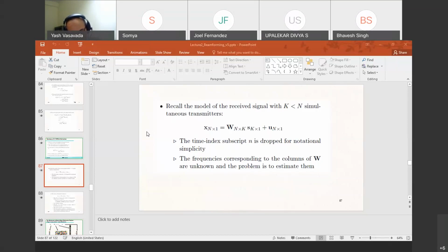In that context, we looked at several other windows, Hamming window, Hann window, the Kaiser window, etc., which suppress the side lobes. But it's sort of like Heisenberg's uncertainty principle, that there is a certain limitation in what you can do.